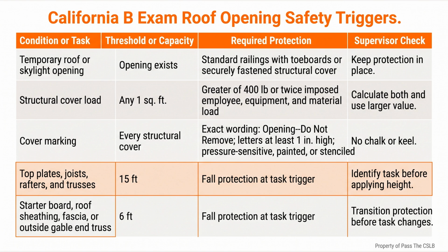I want to leave you with one field sequence. Before cutting, confirm approval, layout, temporary support, weather planning, and opening protection. During framing, trace tail members to headers, headers to trimmers, and trimmers to bearing.